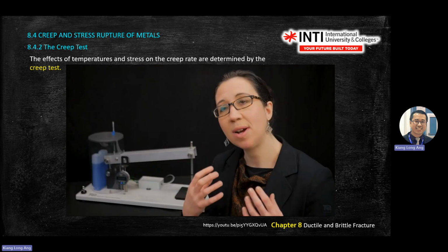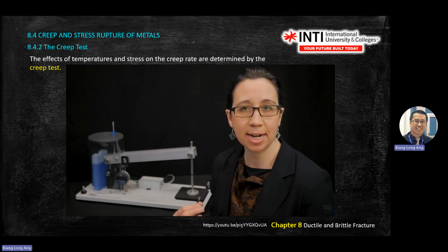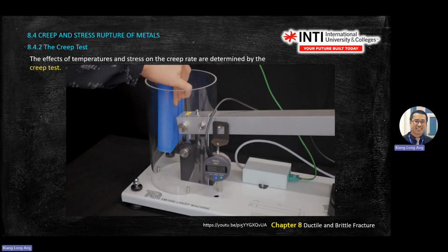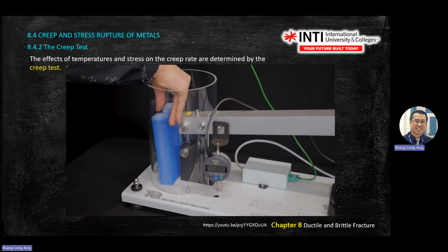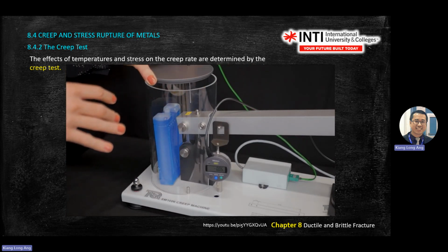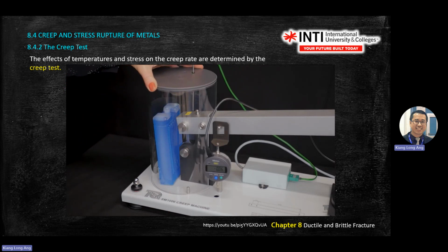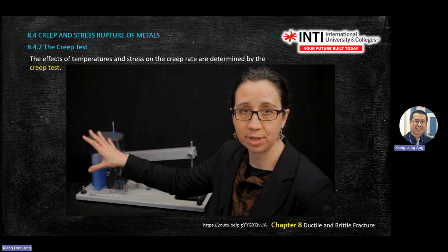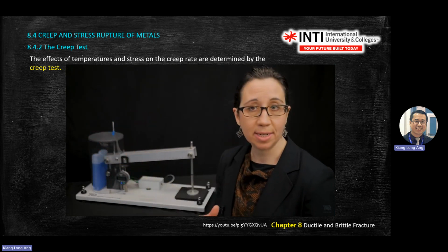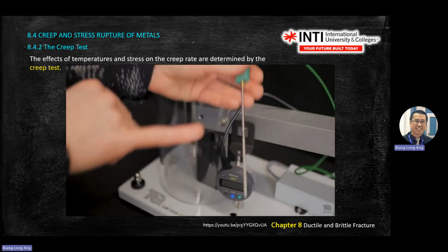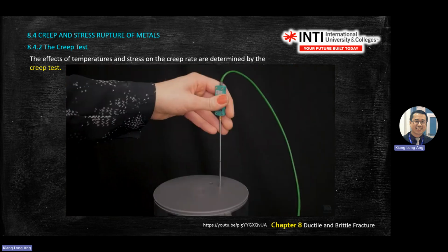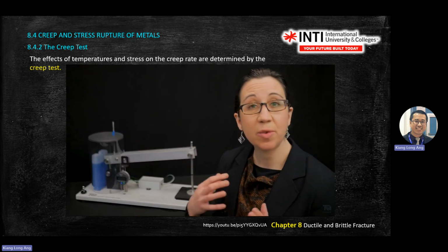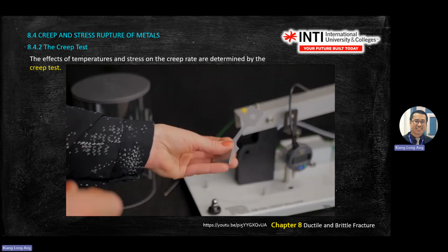Temperature affects creep. This is why the creep testing machine has a clear enclosure over the area where the specimen is mounted to create an isolated zone to help keep the temperature constant, while adding the included ice pack to lower or raise the ambient temperature. A thermometer inserted through the top of the cover measures that ambient temperature. There are additional components included to allow you to measure the temperature using VDAS, including a thermocouple and a thermocouple transmitter. Now we're going to look at the first experiment that looks at creep in different material stresses and temperatures.